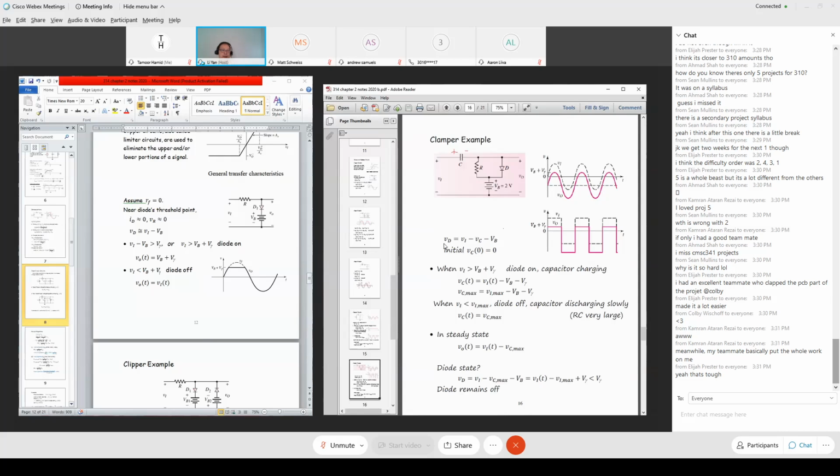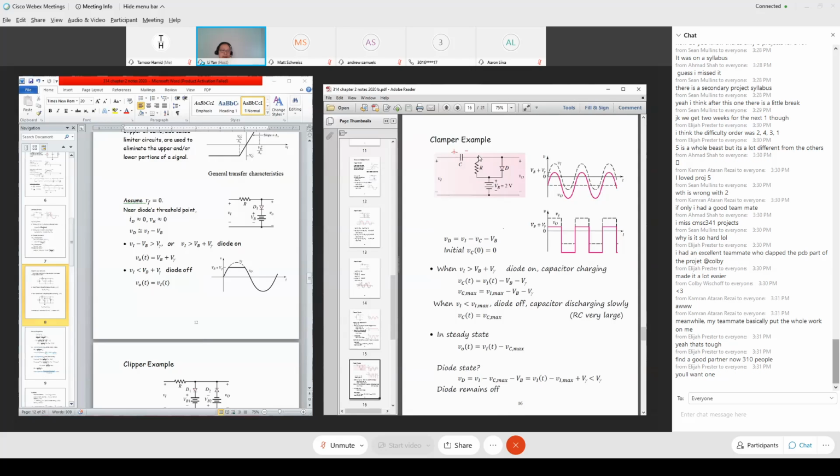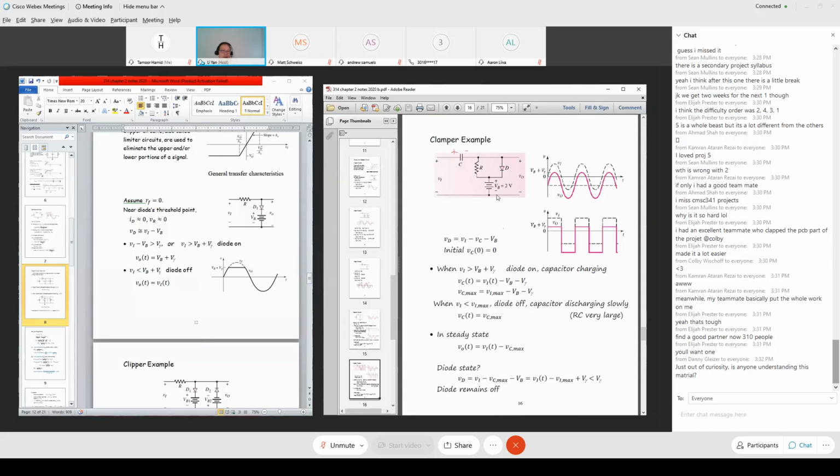Again, I want to express diode voltage in terms of the rest of the voltages. What determines diode voltage? The input voltage, VI. And if there's a voltage drop at the capacitor with polarity plus minus, then input voltage minus capacitor voltage, I get the top. The bottom is the battery voltage. The difference gives you the diode voltage. So VI minus VC minus VB is the diode voltage.